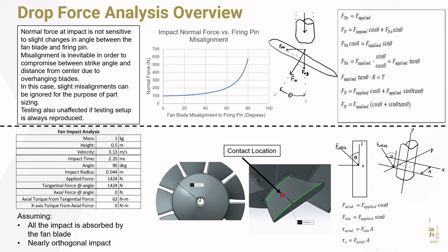The force analysis for each part is done by breaking down the force components of the impact. The goal is to apply forcing to the blade orthogonally to and at the center of the fan blade. This allows the best transfer of energy to the fan blade and prevents us from having to deal with the associated jacking when impacted at an angle. The fan blade roots, where failure is expected, were simplified as cantilever beams, making the math straightforward.